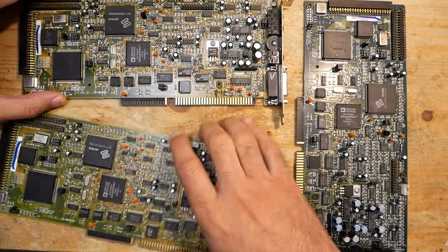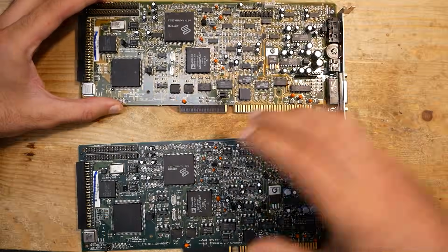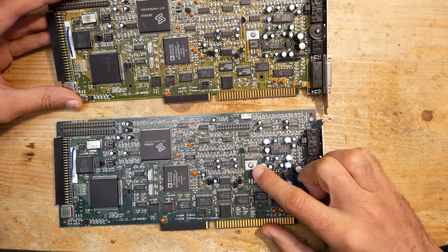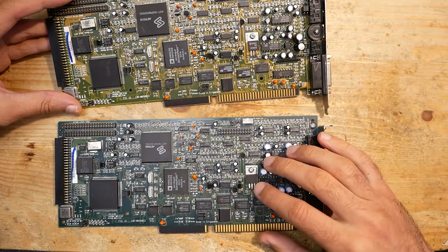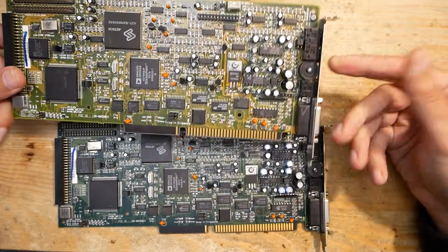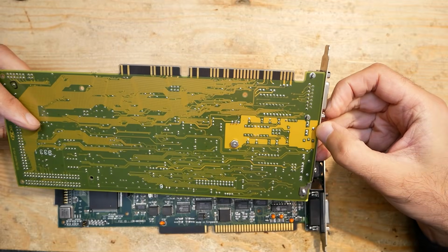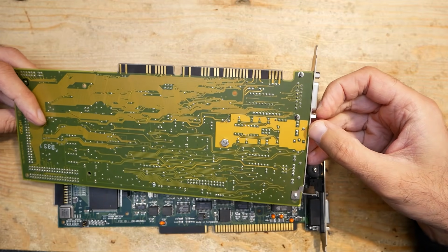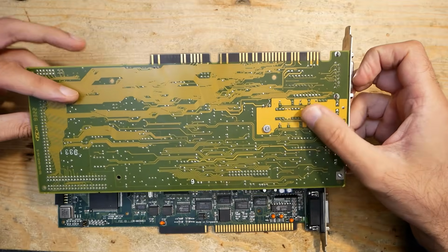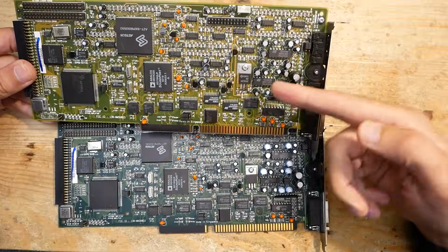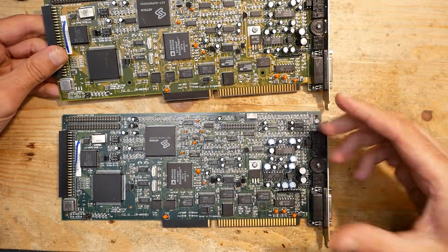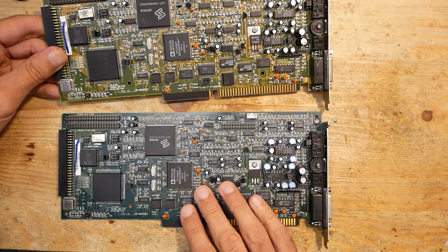These two cards had a very similar problem too. On both cards it looks like too high voltage or reverse voltage was applied. I'm not sure how that could happen, but my theory is that on both cards something wrong was connected to the output. The audio port has a common ground connection which goes to the other places of the card. Maybe 12 volts or 9 volts were inserted here, which ended in negative voltage on the 5 volt rail. I don't know exactly, but this could be the explanation how the chips on this card could have been damaged.